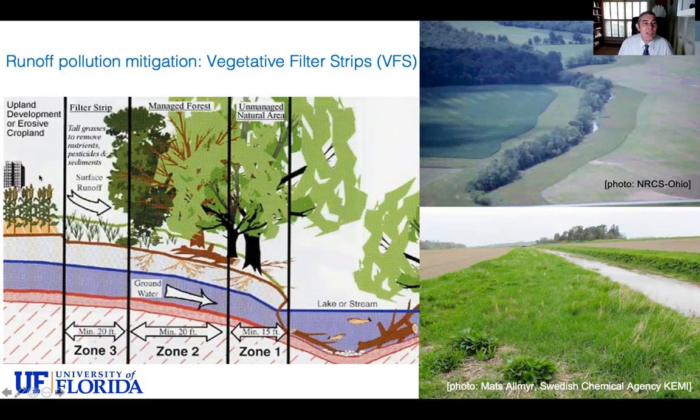Okay, so in here on the left-hand side of my slide, you can see the land use. And again, it could be urban, it could be agriculture, whatever. And then from there are chemicals, but very importantly, the first two phases we're going to be tracing in these chemical pollution events are going to be the liquid phase, the water itself, the runoff, and also the solid phase, which are going to be sediments. Because chemicals are attached either to the sediment or dissolved into the water. So there are these two phases, liquid or dissolved and sediment bonded or particulate. Those two are usually the ones that answer for the transport of chemicals.